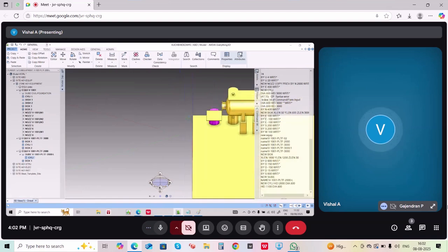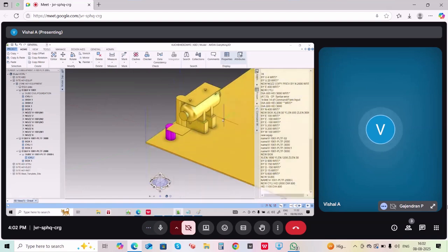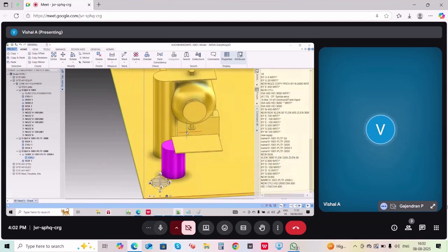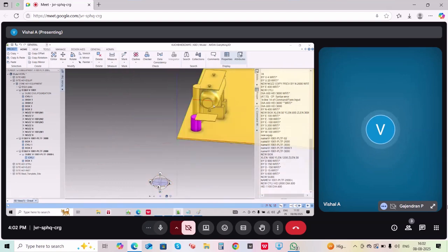Now one more thing. Always remember, nothing should get obstructed. Why I created this ladder here also is because I know that all my piping will go from this side, because we have a bottom nozzle also. The pipe will come out and then it will go like this. If you have a top nozzle, the pipe will come out and drop and then go like this. So anything that happens will happen here only. So that you need to understand.